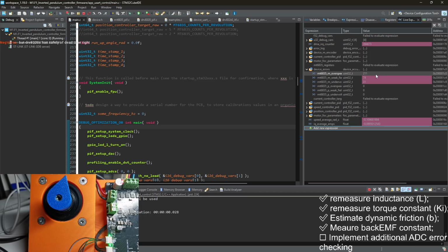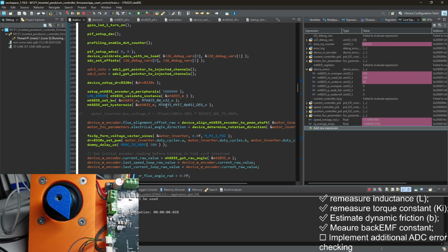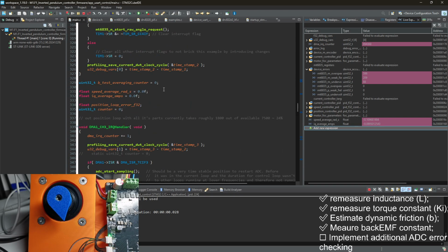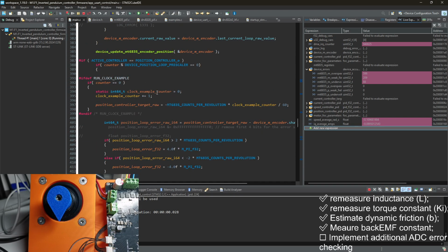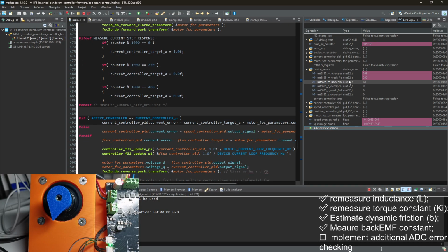Because in pure current mode, we don't have any. Oh, we do have them because our cable is longer. The length of the cable also matters, actually, which I figured out, and I think it matters because my pull-up is not strong enough. I should probably use not 200 as I soldered yesterday, but something like 400. But I will not resolder it, given how much of a pain it was yesterday. So these errors don't break anything, and I'll allow it for now.